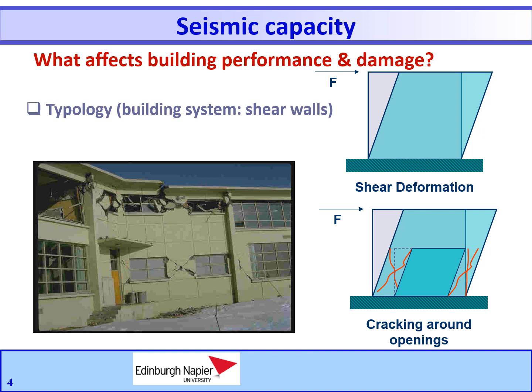Not all of these buildings were well conceived structurally, and because of the ease of adding or deleting walls and openings, torsional problems became common. Current design approaches promote the benefits of confined concrete columns and ductile concrete frames, or dual systems of ductile concrete moment frames coupled with confined concrete shear walls.